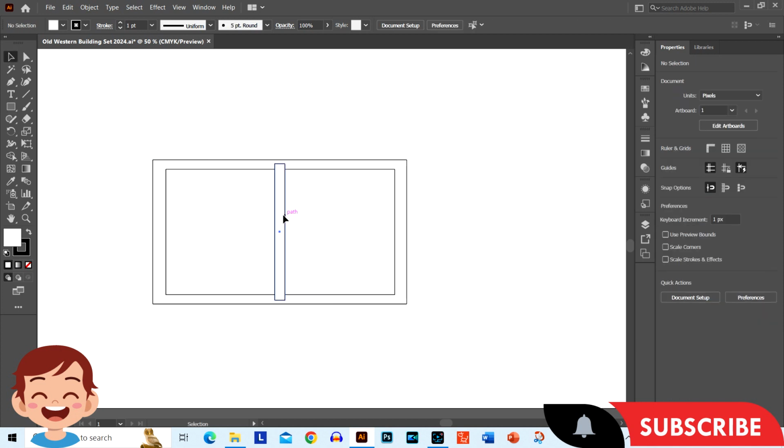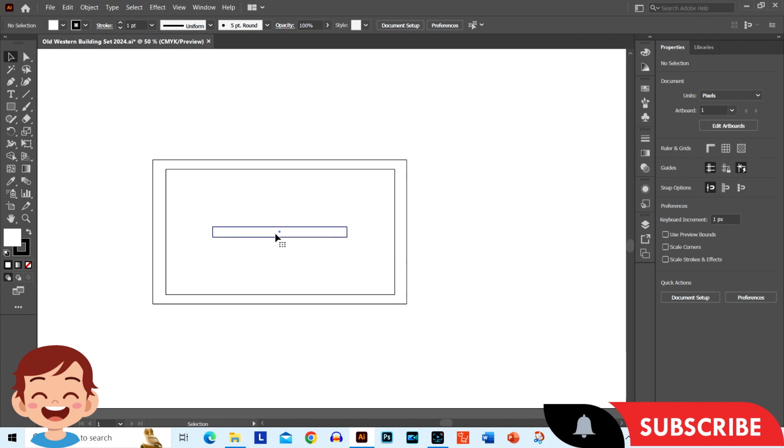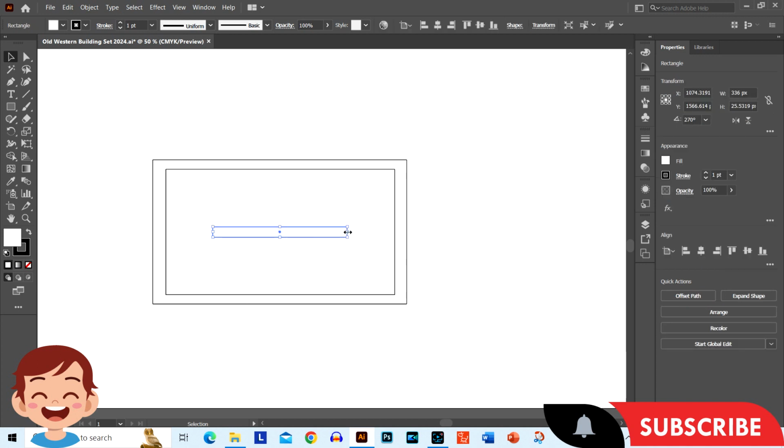It's centered. Now if I want it to be in 4 different areas, I just go like this. I just press R on my keyboard, I rotate it. And just hold down shift at the same time. I rotate it like this. I'm going to make a copy of it too once I finish this. So I just quickly move it out here. Control Z. Just a little bit too far, and that looks better.